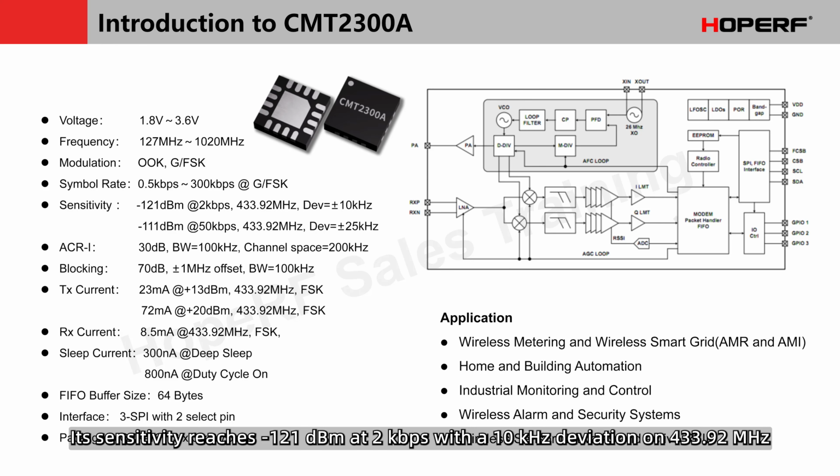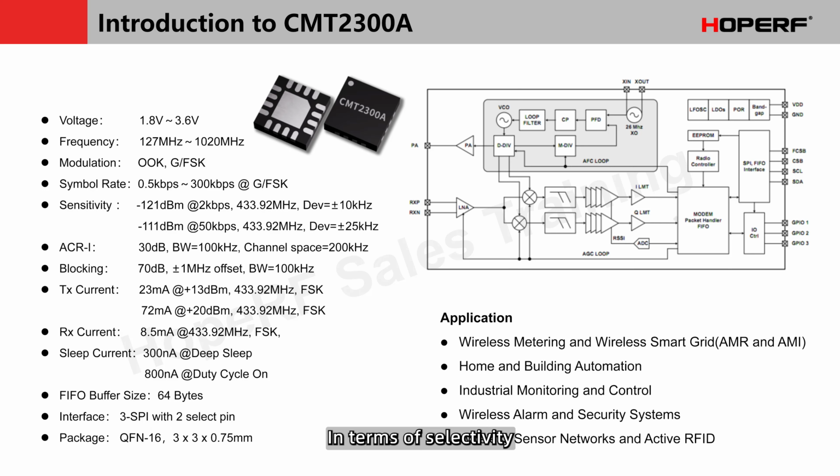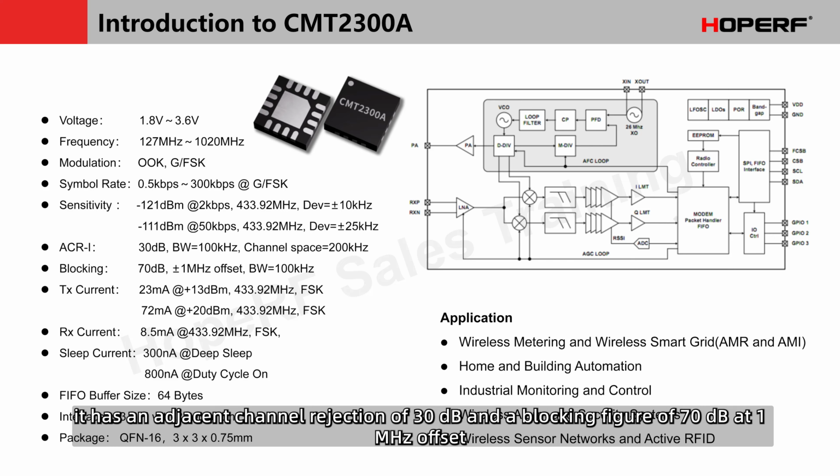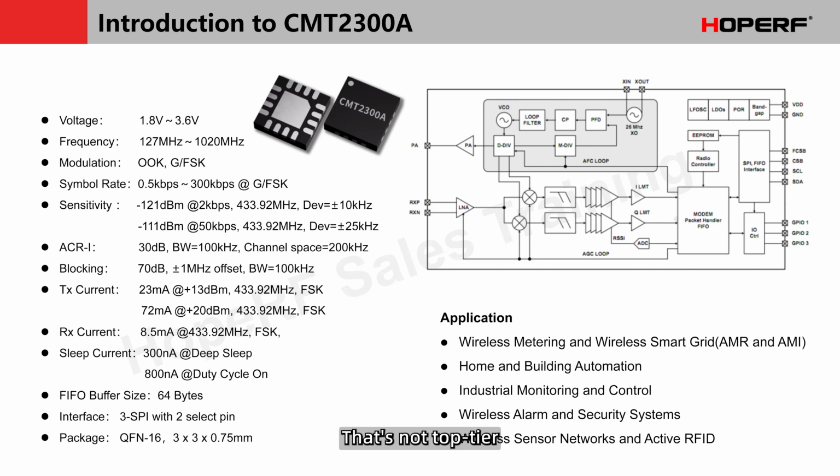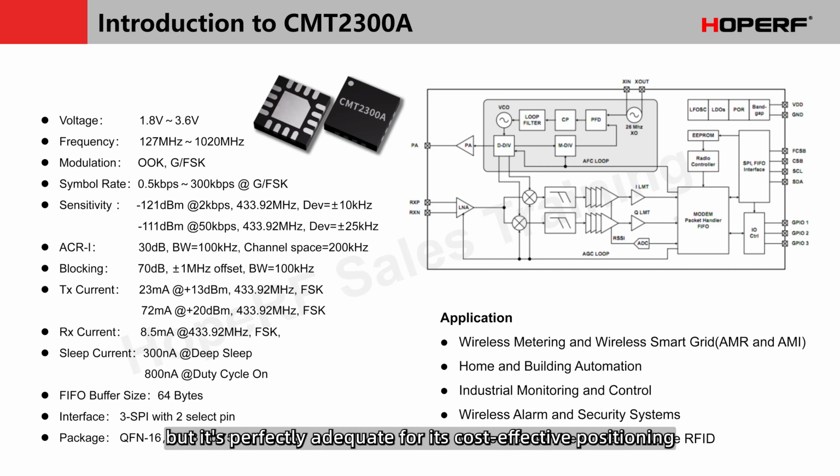Its sensitivity reaches minus 121 dBm at 2 kilobits per second with a 10 kHz deviation on 433.92 MHz.